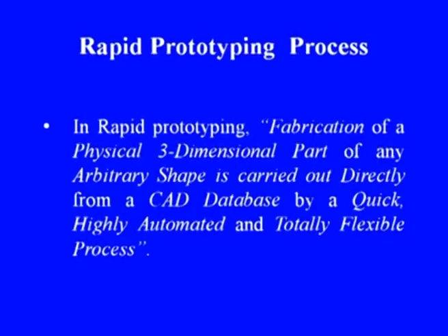Rapid prototyping processes. In rapid prototyping, fabrication of a physical three-dimensional part of any arbitrary shape is carried out directly from a CAD database by a quick, highly automated and totally flexible process.